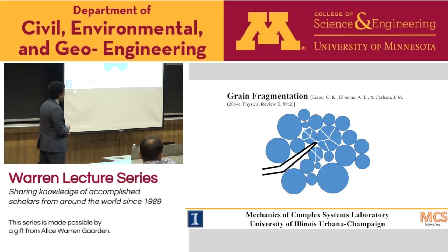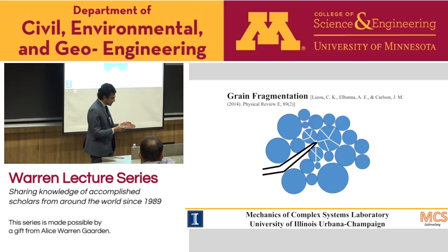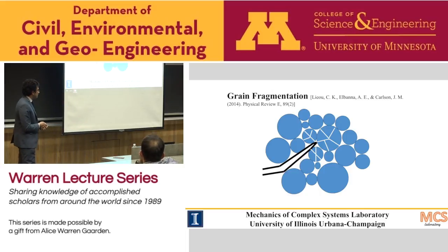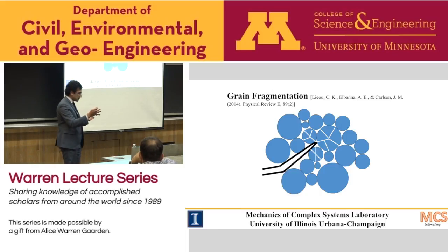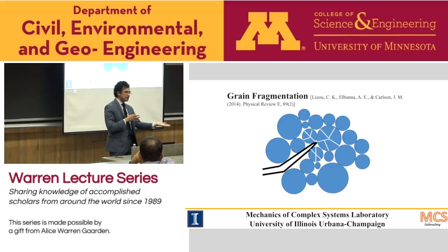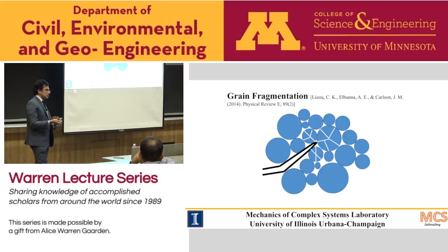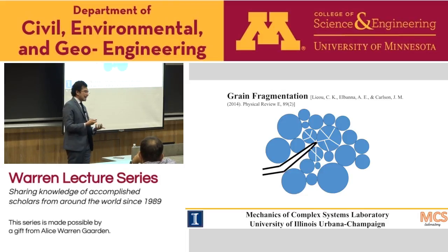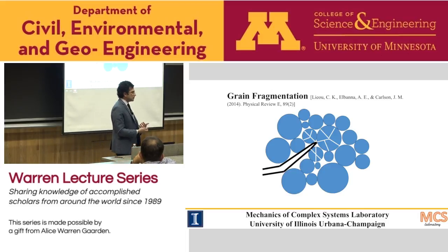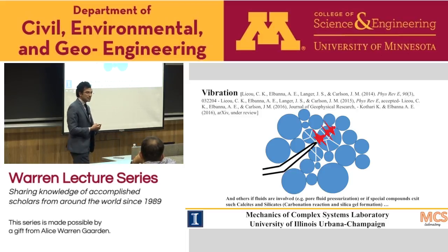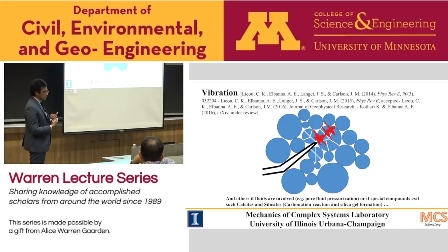A third avenue that we started pursuing in the last year was to understand the effect of vibration in granular material, and I will focus a little bit more on that in this presentation. You can think of it this way: if you shear a granular layer, then it dilates. If you vibrate a granular layer, then it tends to compact. So what if you have both of them active together? Then there is a competition between dilation and compaction,